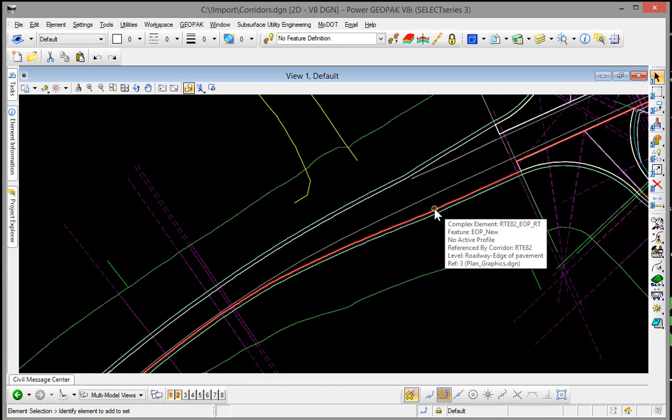And when you target it as an alignment, as linear geometry, then it doesn't have to scan all of the different graphics out there. It only looks for that one alignment name and hits that and makes it a much more efficient process. And so imagine doing this hundreds of times over a project where all of those targets have hundreds or even thousands of PIs. It really will make a difference on a large job. If it's a small job, using the template to target a known feature name is perfectly acceptable.